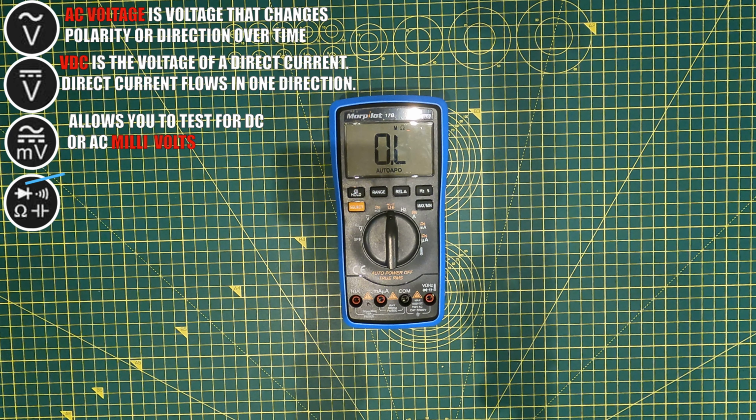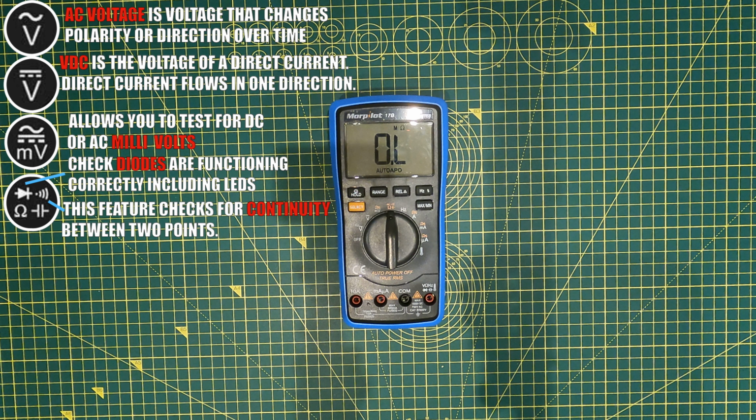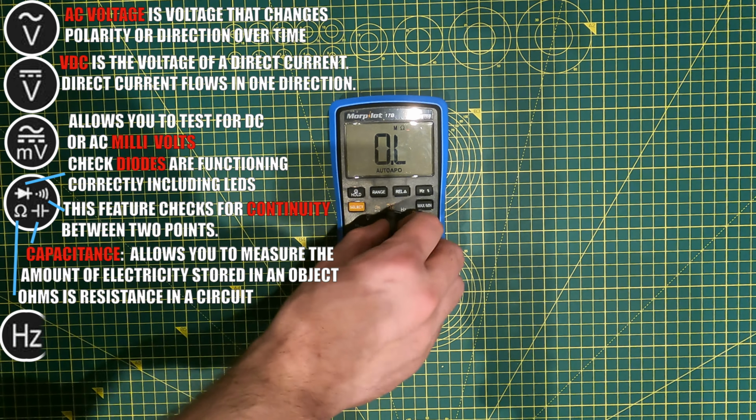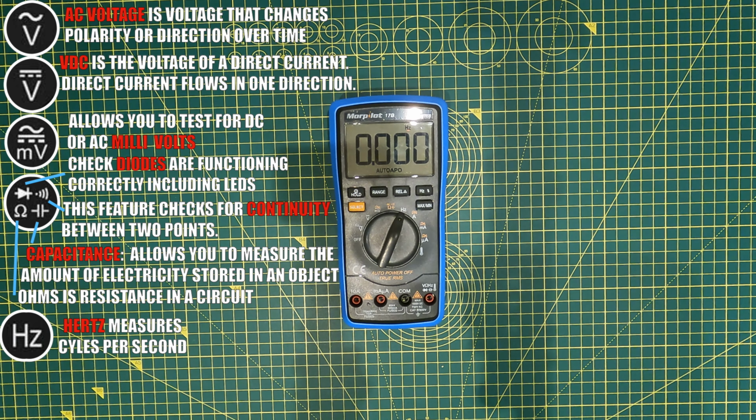First symbol is a diode check symbol, which allows you to test LEDs and diodes. Next you have the continuity feature, which allows you to check you've got a complete circuit. You then have the capacitance symbol, which ensures your capacitor is working properly, followed by the ohm symbol, which allows you to measure resistance in a circuit. You then have hertz or frequency, which tells you how many times a second the current changes direction.